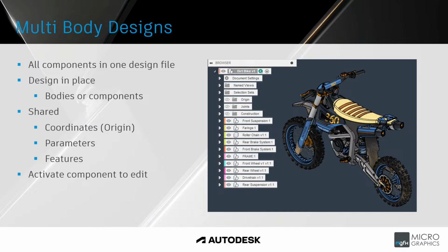You can create a feature and select those three components to make that hole through them, to ensure correct alignment. For something like this motorbike, we could have an extrude that creates a hole through the frame and the swing arm, so that we have that pivot point for the swing arm and it lines up perfectly between the two components.